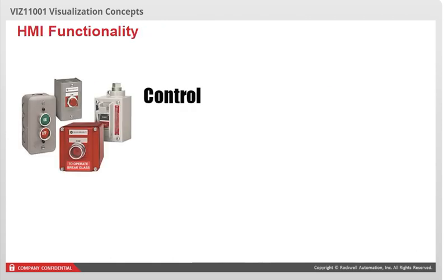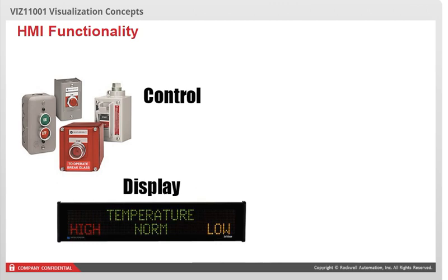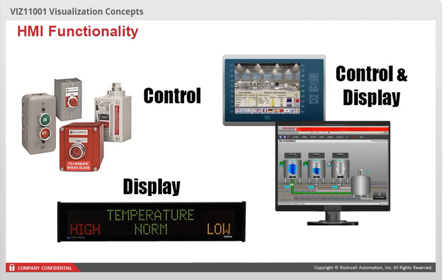The most basic HMI devices transfer information in a single direction. That is, they send information to the system or they indicate status. Most status or output devices in this category are limited to displaying only alphanumeric information, such as alarm messages and part quantities. More sophisticated HMI devices offer both input and output data transfer. They typically contain additional visual tools and options which assist in both understanding and modifying the process. These much more flexible visualization solutions will be the focus of the remainder of this module.